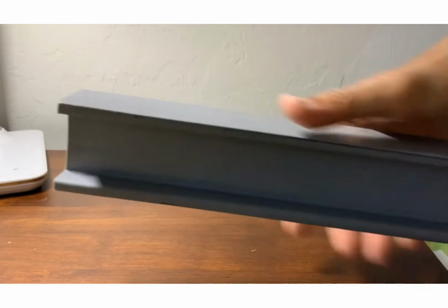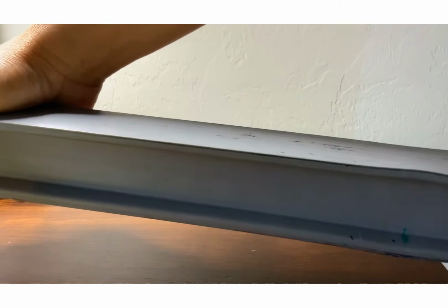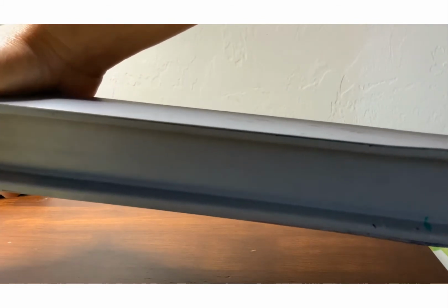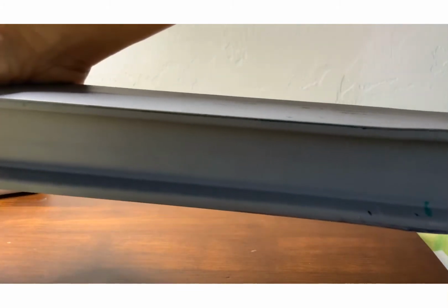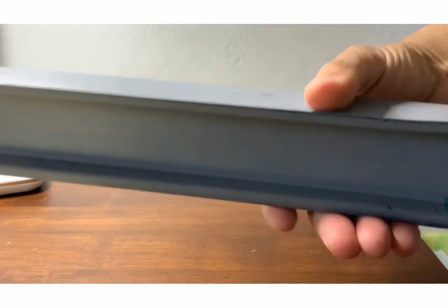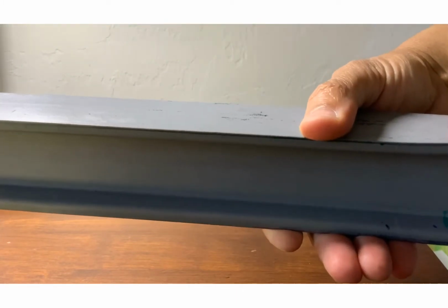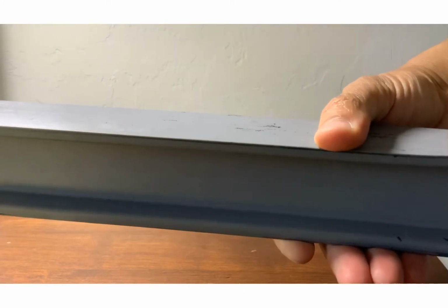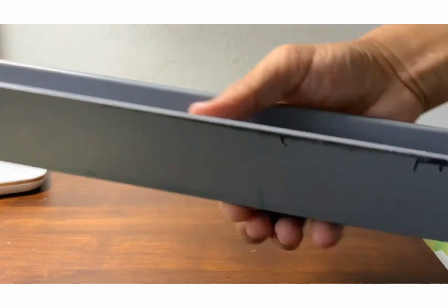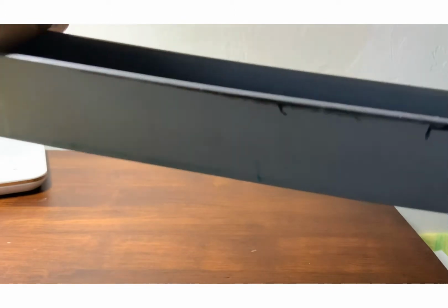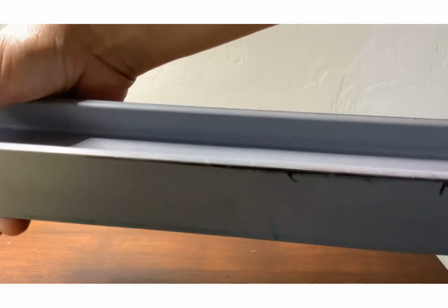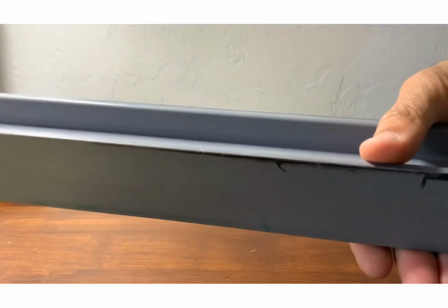For that reason, if you go to a Costco warehouse or Walmart or Publix, etc., you see the beams on the roof always lay this way, because this orientation gives a greater area moment of inertia. It means less stress on that body with the same moment. If we put the beam the other way, it is Iy, and that will create more stress on the body.